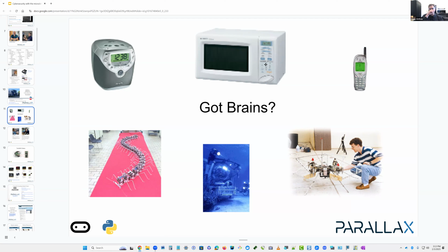For example, with the microwave oven, you also end up pressing a button on the keypad over here on the right. Again, the microcontroller inside detects that circuit change. It'll send rapid high-low signals to a speaker inside the microwave oven to create a beeping noise to let you know that it knows you pressed the button, and then it'll update the liquid crystal display and do other functions like turn on relays that allow power to the microwave emitters and the rotating plate at the bottom of the oven, and so on and so forth. So that's the way microcontrollers are used in commercial devices.